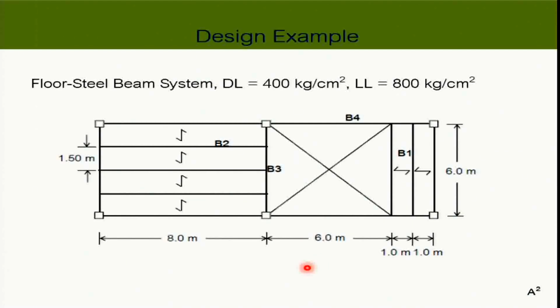B3, for example. This B3 supports B2. So in turn, it means that B2 can help prevent B3 from moving sideways. And that also means the unbraced length of B3 becomes 1.5 meters. Right? Beam B3 can dance, but with the unbraced length equal to 1.5 meters.